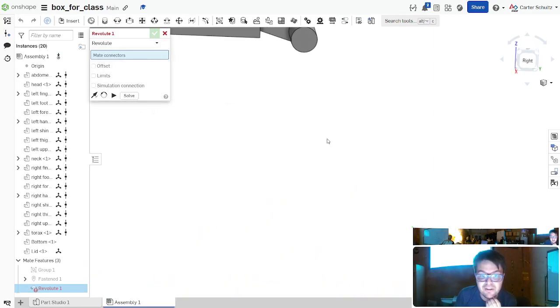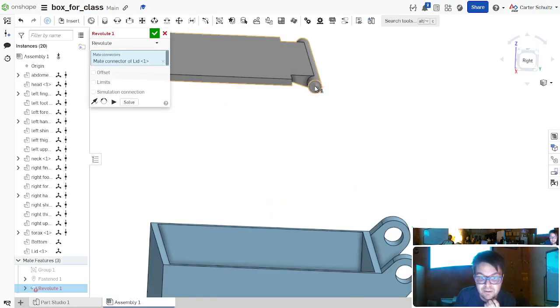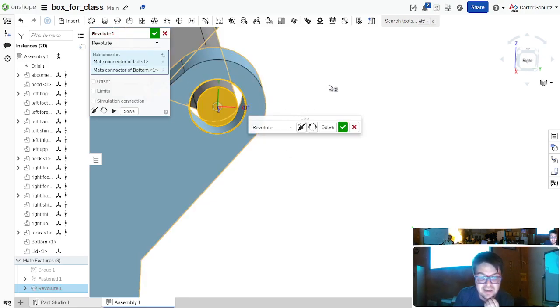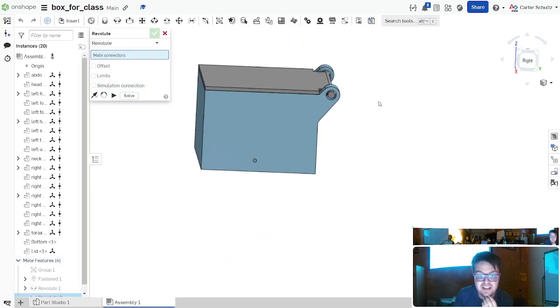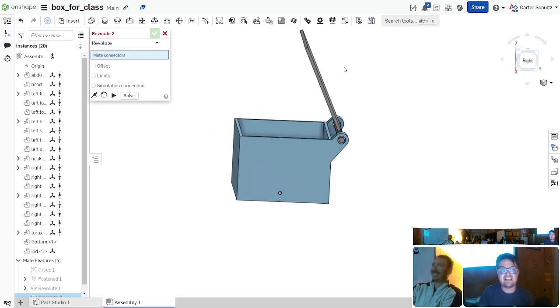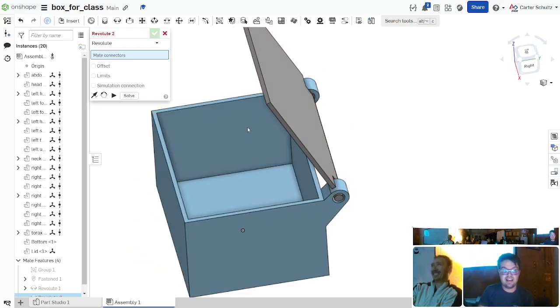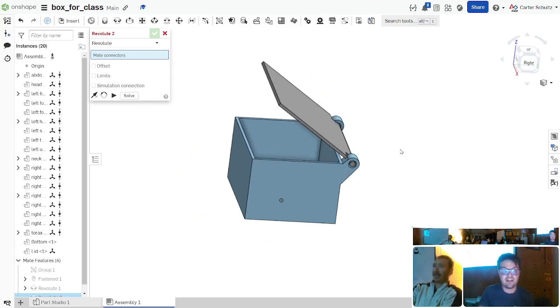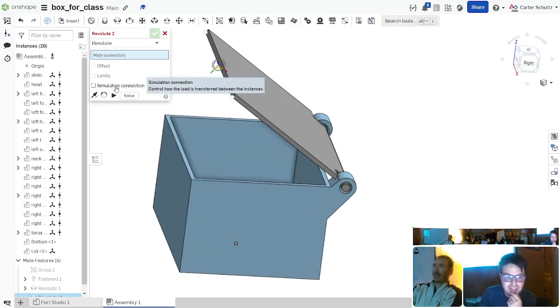Perfect. I'm going to go to the end of the pin here and stick it right there. I'm going to slide over to this. I'm just going to hover in space here and it will automatically find that edge for me. Boom, there, done, click. They're constrained to each other. That easily, and they can now manipulate and move.